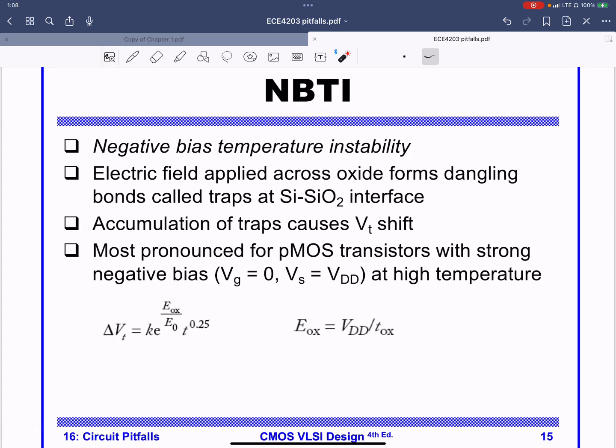The other issue is that even with the supply voltage being correct, if the device has elevated temperature for a long time, an electric field across an oxide can be causing that oxide to change by itself.